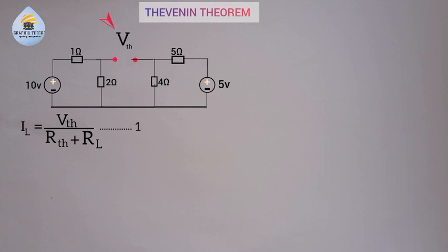You can see that? Now, we want to know the Thevenin voltage. The Thevenin voltage is the potential difference between these two terminals, let's say terminals P and Q. That will be the Thevenin voltage. So now, calculating for VTH, I've removed the load.